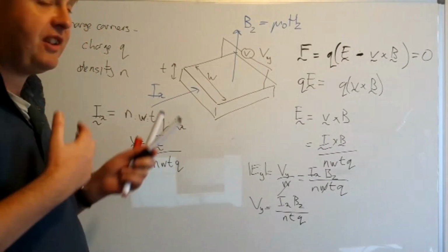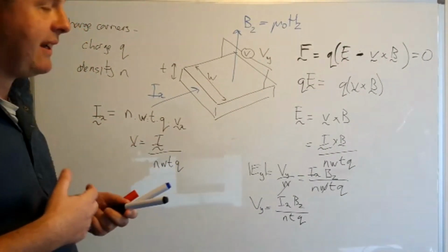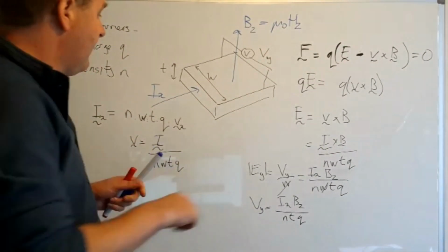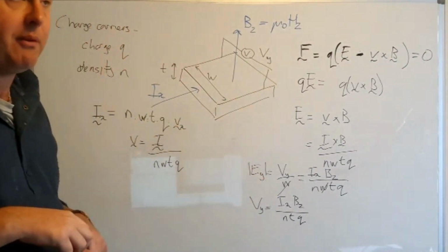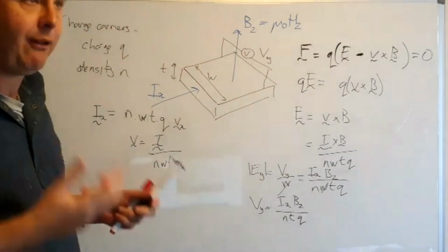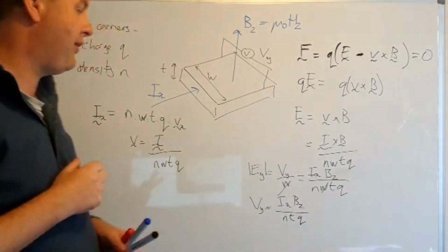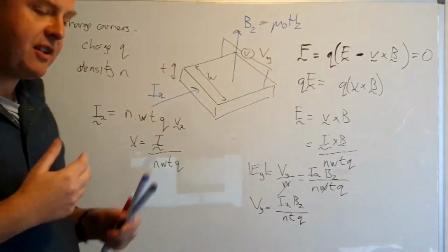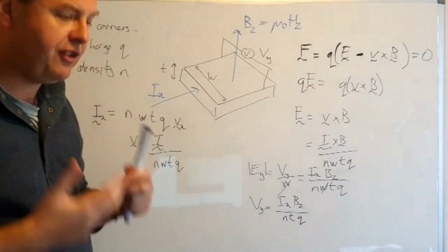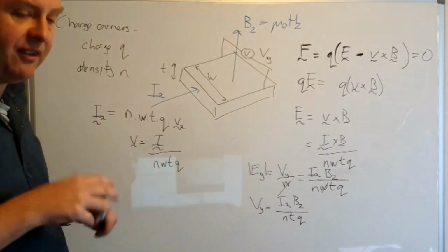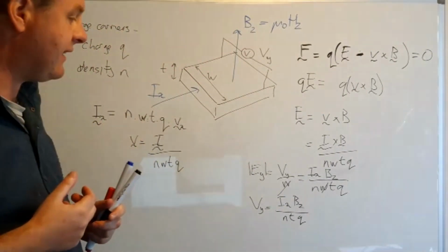Of course, the disadvantage of that is that these systems tend to have quite a high resistance running in the x direction, which means if you put the current up, the Ix, too much, you end up dissipating a lot of power in your sensor. And that may not be a good idea for other reasons. So this is what I mean by trying to introduce the concepts you've learned in solid state physics into understanding how to design a good sensor.